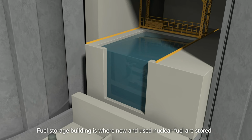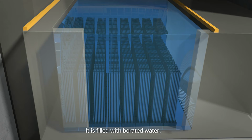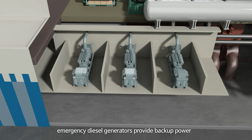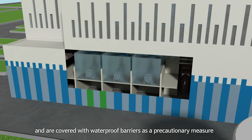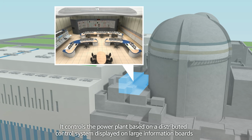The fuel storage building is where new and used nuclear fuel are stored. It is filled with borated water, which inhibits nuclear fission reactions, and the fuel is cooled here for at least 5 years. In the event of a power outage due to an accident, emergency diesel generators provide backup power. The emergency power facilities are all located above ground and are covered with waterproof barriers as a precautionary measure. The main control room is the space where the power plant is managed. It controls the power plant based on a distributed control system displayed on large information boards.